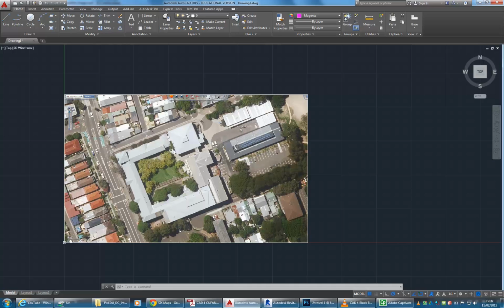And that's going to be really useful when we work on it there, so you don't need to keep it at this angle in order to work with true north in Revit, in other words. And that means I can rotate it so that it makes more sense with these buildings that we have. So we're working on this building and this building, and it'll make a lot more sense if they're at a right angle to the page, or perpendicular and parallel with the page.